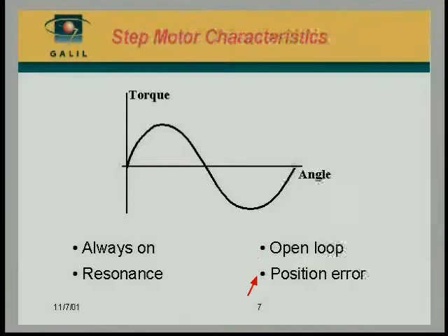One more point to clarify, it's a position error. When we tell the motor to move to a certain point by energizing the phase, we expect the motor to move here. But if the system had some friction, for example, at that level, the torque would push the motor toward the equilibrium point. However, at some point when the torque equals the friction, the motor would stop, resulting in a position error, the difference between the stopping point and the equilibrium.